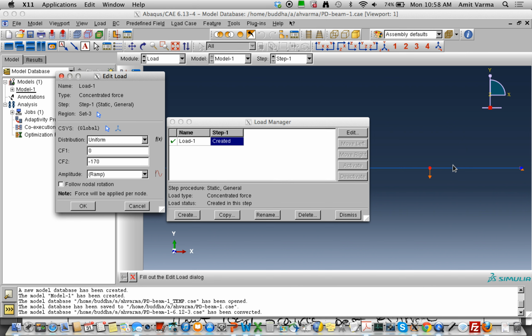It's obvious, at the same point, you can't specify both the load and the displacement. You can specify one, either the load or the displacement. So if you do the analysis in load control, then at that node, you can pick up CF2, which is the concentrated force it's applying. So you'll plot CF2 versus U2. But if you're doing it under displacement control, you'll have to plot RF2 versus U2, because there'll be a reaction force at that node. It will condense out that displacement. I'm sure you're familiar with static condensation. Because you're specifying a displacement, it will statically condense out that individual degree of freedom, and it will appear in the reaction force when it completes the problem solution, rather than in the applied load.